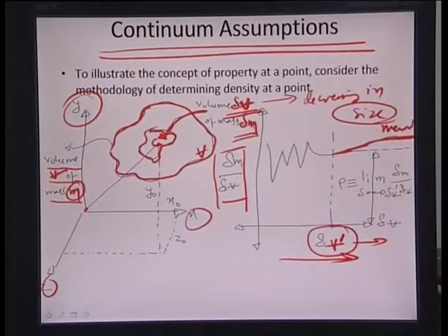But below this you can assume that the dimension is so small that one of the characteristic dimensions is more like the dimension of the mean free path of the molecules. So if the volume is small and the mean free path is greater, there is an uncertainty of whether the molecule is within the volume or outside the volume. There are thousands of molecules crisscrossing the surfaces of this small dimension, and therefore you are not 100% certain how much mass or how much volume is there within the infinitesimally small point volume that you are considering. Therefore, the density should be a function of time.